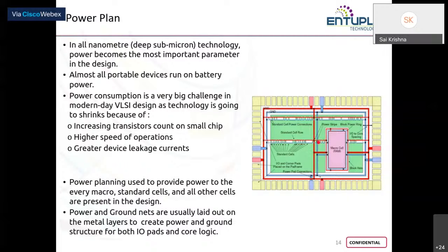So they are your power strips. Here, just to avoid the clumsiness, we have only taken one set of strips, but normally when you deal with industrial level designs, we take a group of strips which form a complex mesh. Along with the power rings and strips, you also create rails for your standard cells, wherein from the complete setup they tap in power and operate.